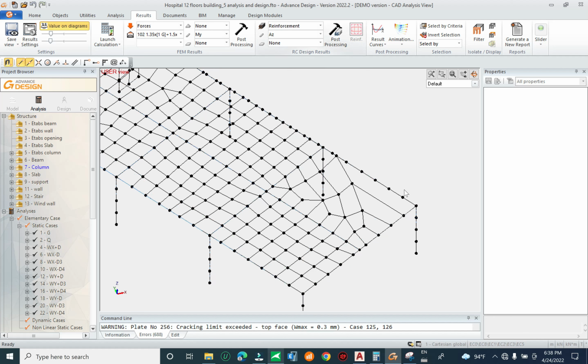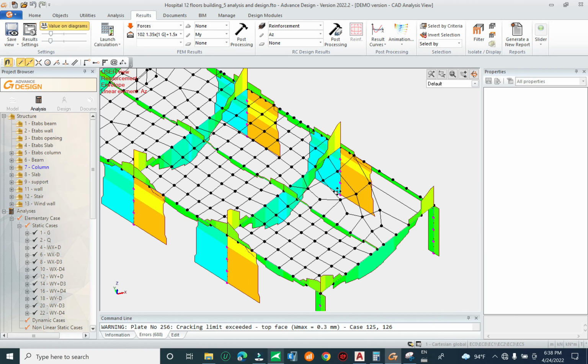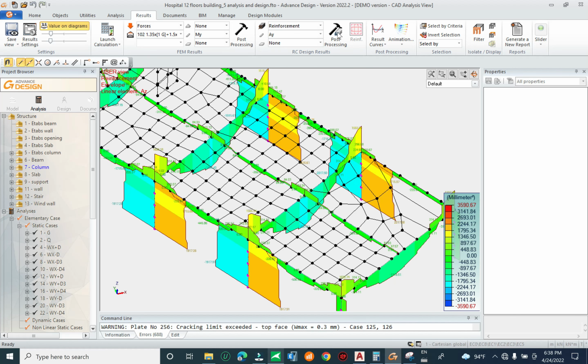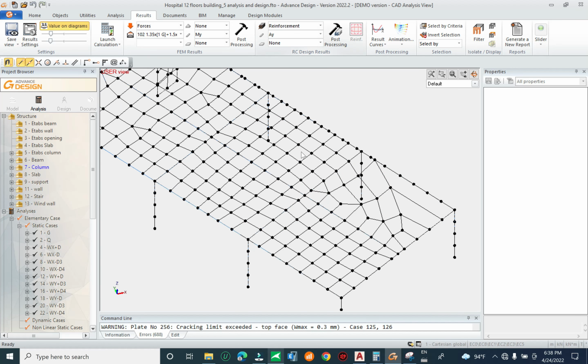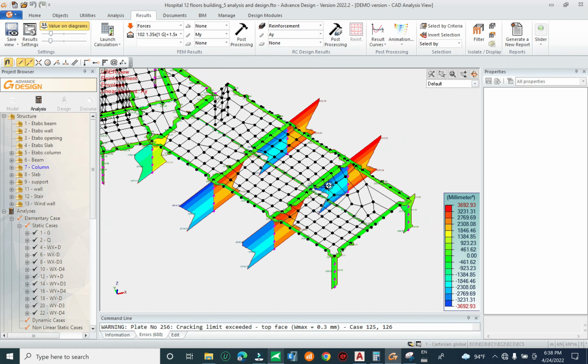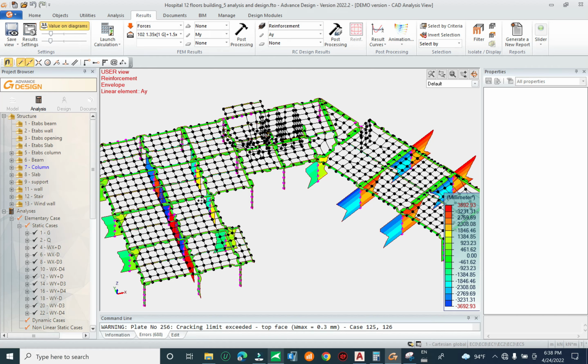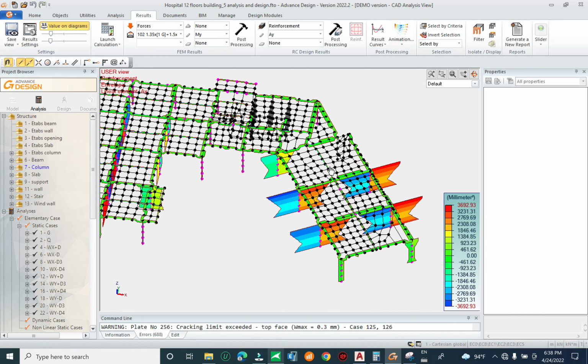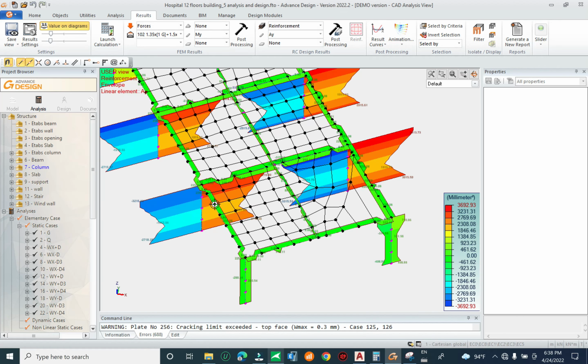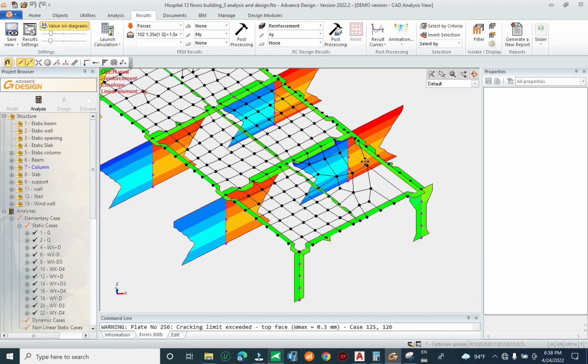In the column, you see here in the back axis, you need more rebar. You need around 34 and around 31 in one face. Okay, in the face you need 34. Now let's check about 34.